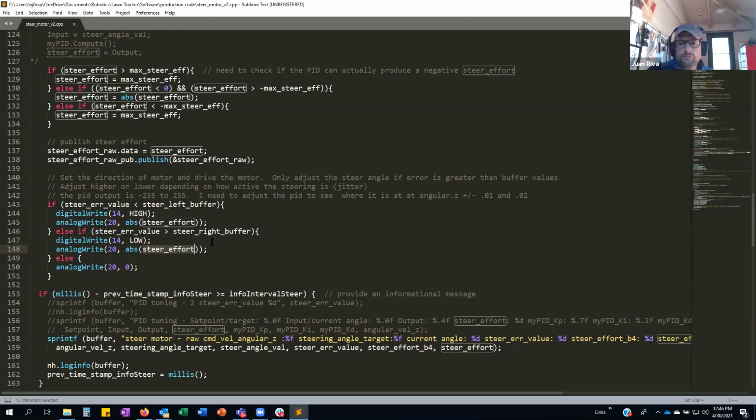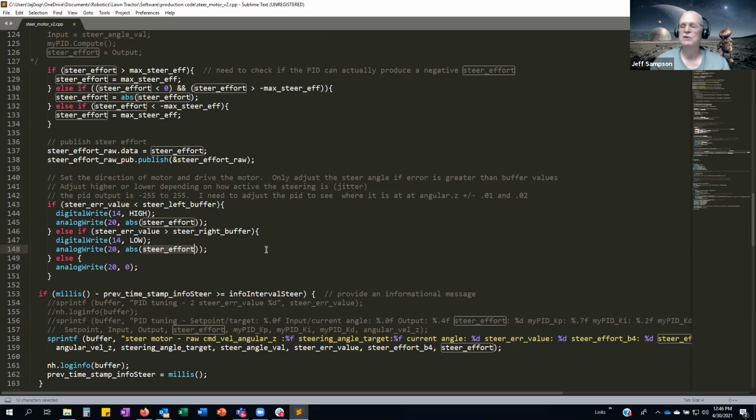It's because that's the default PWM routine. It's only like 500 hertz or 400 hertz or something. And probably I'm going to go looking around on the Arduino and see if they've just got a different command that's smart enough to give you a higher frequency PWM, in which case that would stop the whining. Otherwise, there's other ways to get around it, but it's annoying enough right now sitting on the table next to me. I'll probably look into it fairly quickly, how to fix that.